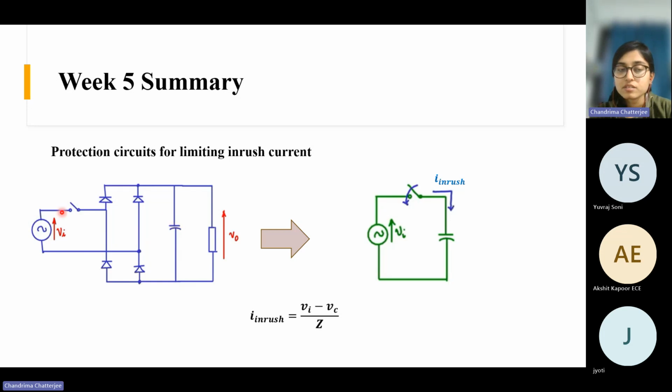whenever you are paralleling one voltage source with another voltage source, the capacitor stores charge, right? And that's why some voltage comes across this capacitor. For a capacitor, the voltage doesn't change drastically. It retains the voltage. That is the property of a capacitor, and that's why we use a capacitive filter, so that the fluctuation in the output voltage reduces. Now the problem arises because when it has reached steady state, it is okay.